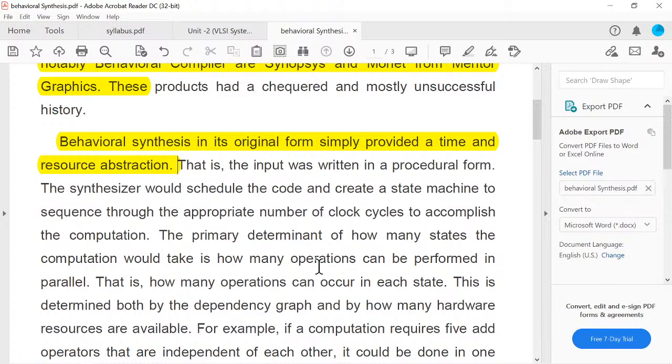At that time it is suitable for the designer to start from gate level. But when the number of gates increases in the circuitry because of the complexity of the circuit, what can we do? We can't start from the gate level at that time. So at that time we start the circuit synthesis by using the RTL level, because if we start synthesis of a circuit by using gate level, it is a very time consuming process.